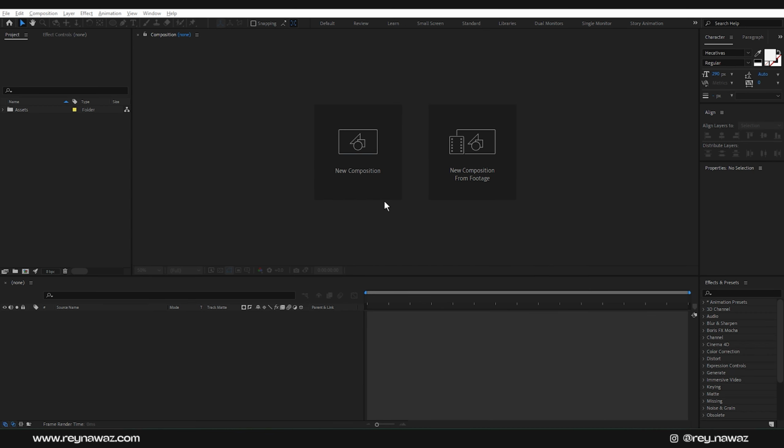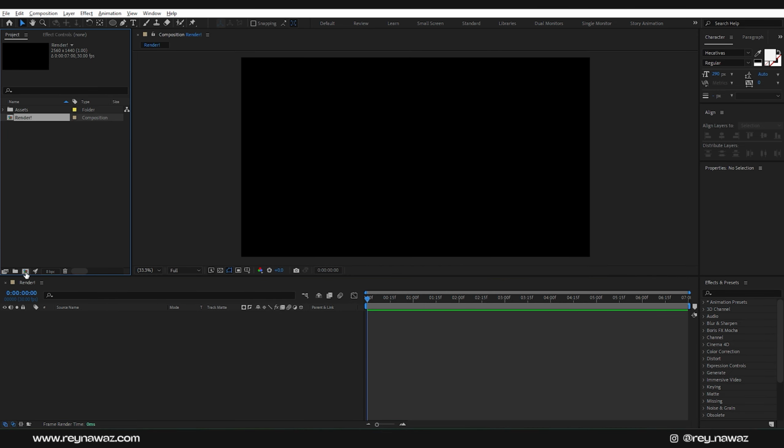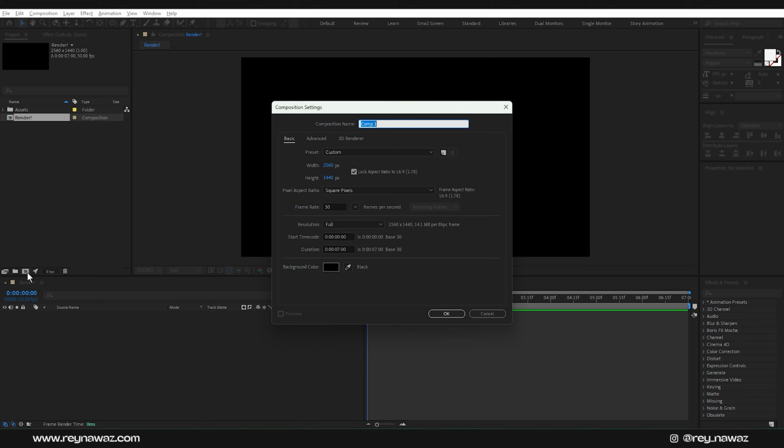Alright guys, here we are in After Effects and let's start by creating our first composition by clicking over here and rename it to render as our main render comp. Width and height is 2560x1440. You can also go with 1920 by 1080, 30 fps and 7 seconds long and hit OK. Again go over here and create a new composition and rename it to assemble. In this composition we will assemble our entire scene, properties same as our previous composition and hit OK.